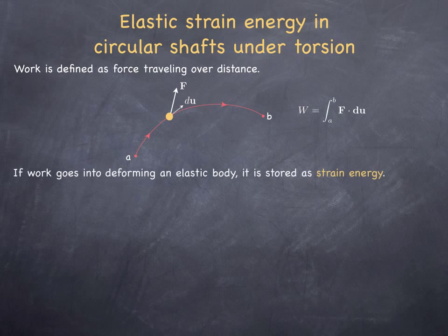And if I'm looking at an elastic problem, then all the work carried out by the conservative external agents will be stored as strain energy inside the system. So if I apply all the torsion, concentrated or distributed torques on a shaft, they will then increase the internal strain energy of that shaft by the amount of the work that they have done through those deformations.